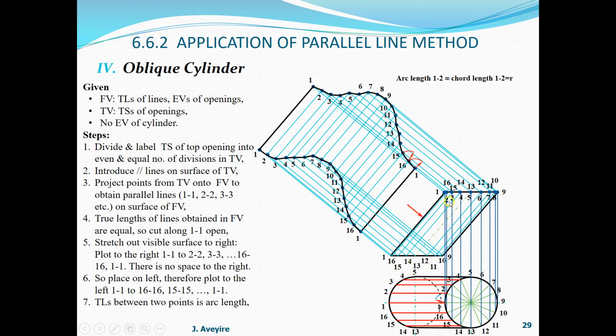To obtain that, we project along the true length, and that is along this line. And when we project, for that, we need a mutual projector, then our mutual reference line that is over here. So you see here you have negative measurement here and positive measurement here. Likewise, the reference line to AP is over there. So you have negative values here, positive values here.